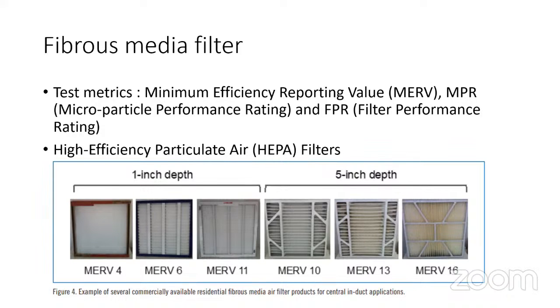So the fibrous media filter, looking at them closely, the fibrous air filters remove particles by capturing them onto fibrous filter materials. These media filters vary widely in their ability to remove particles. Their removal efficiency depends on multiple parameters like particle size, velocity, filter thickness, filter porosity, etc.